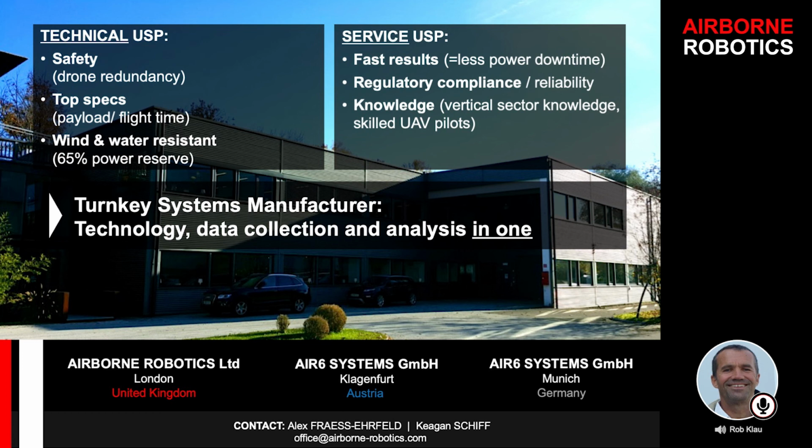And having a LiDAR surface to put your photogrammetry onto as well can speed up processing and create better results. So it is a big, complex topic. I'll just go back to the accuracy point though. If all of your inputs are high quality and accurate, then all of these different data types come together quite nicely. If they're not, then it's a monkey puzzle of stuff. So I'll just bring it back to the accuracy point there.